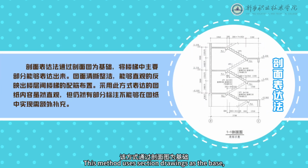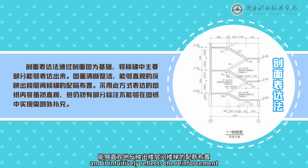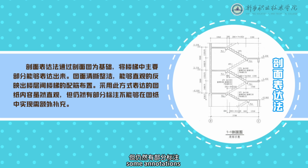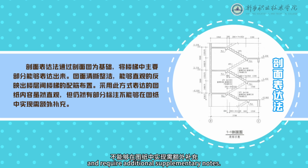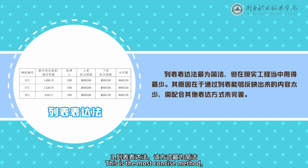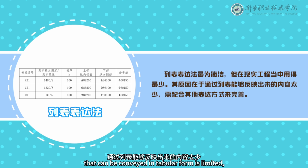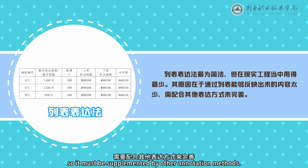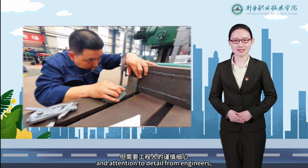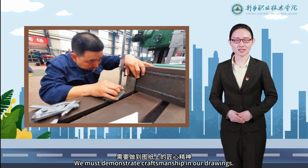This method uses section drawings as the base, clearly presenting the main stair components. The layout is clean and neat, and it intuitively reflects the reinforcement arrangement between floors. Although this method is intuitive, some annotations still cannot be fully conveyed in the drawing, and require additional supplementary notes. 3. Schedule annotation method. This is the most concise method, but it is the least used in actual projects, because the amount of information that can be conveyed in tabular form is limited, so it must be supplemented by other annotation methods. Though stair construction drawings seem simple, they require meticulous care and attention to detail from engineers, which is essential for ensuring overall construction quality. We must demonstrate craftsmanship in our drawings.